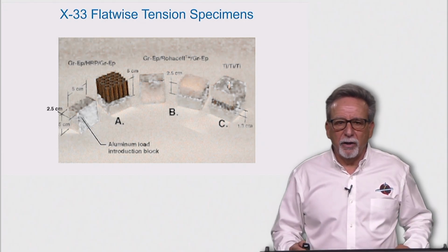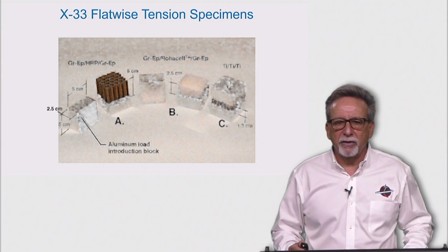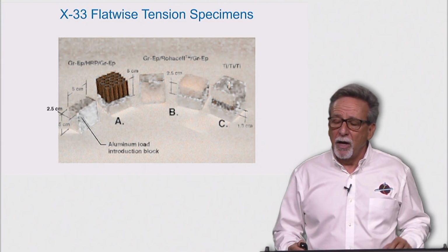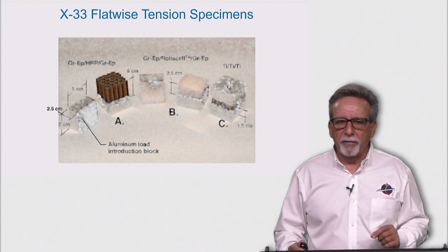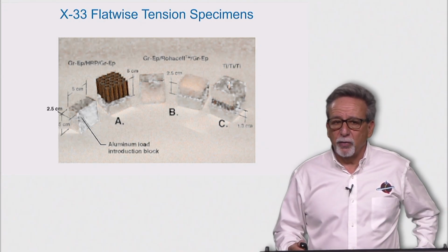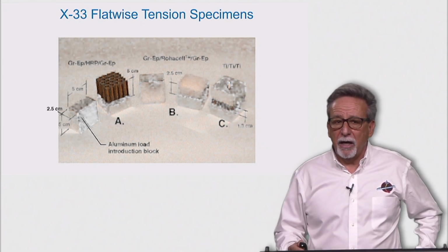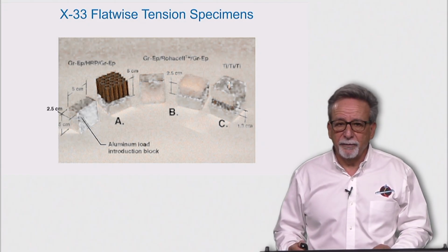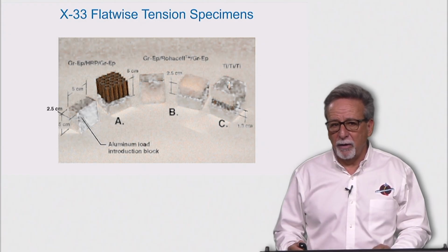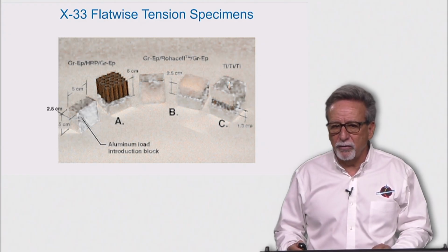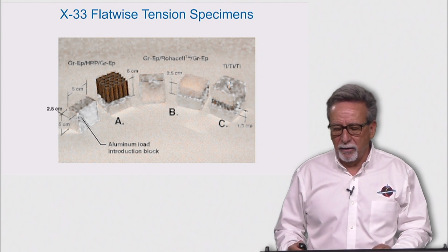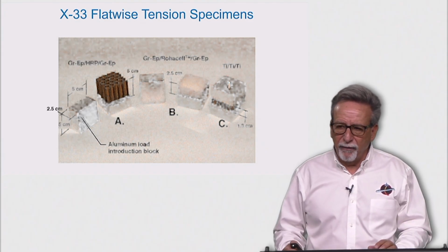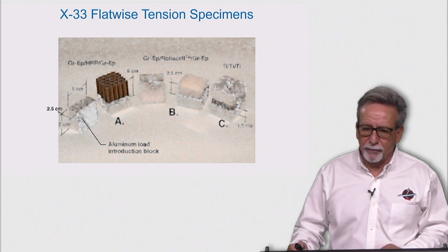Shown here are some of the failed honeycomb core specimens and core flatwise tensile tests that were tested. We tested these specimens at cryogenic, room temperature, and elevated temperature. These tests were critical to determining the ultimate hot and cold bond strengths of the material and the material fabrication procedures used for full-scale honeycomb tank manufacture. These test specimens were used to evaluate many different materials, combinations of materials, and bonding agents for various portions of the trajectory under varying thermal and mechanical loading conditions.